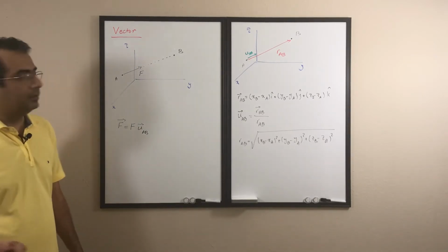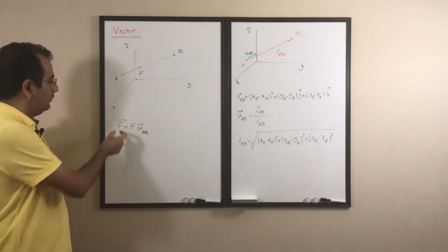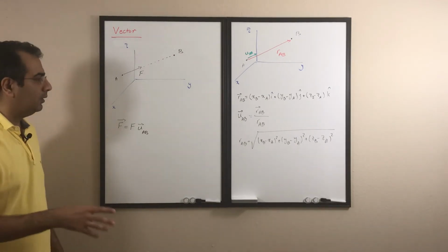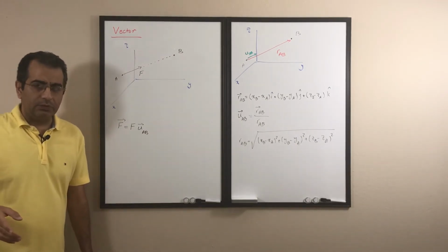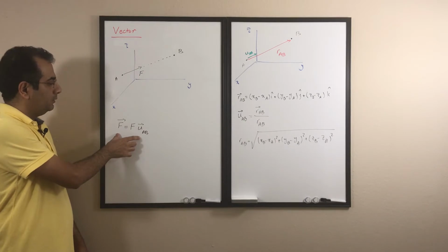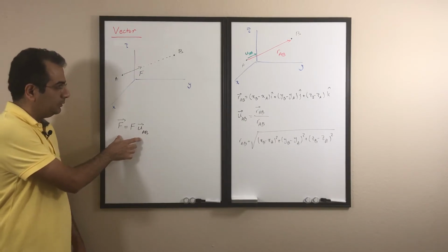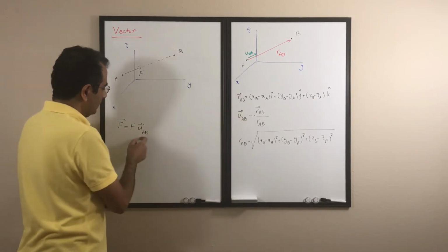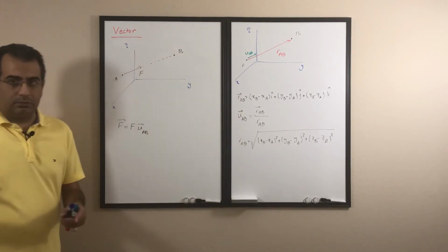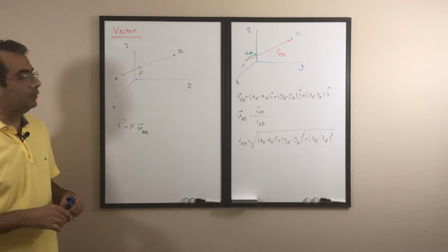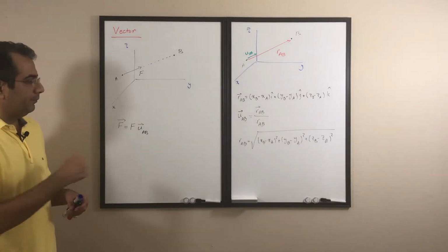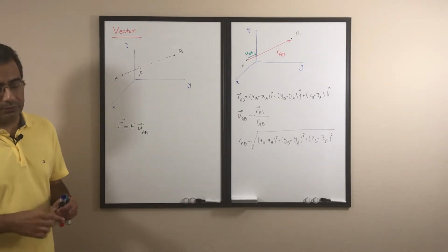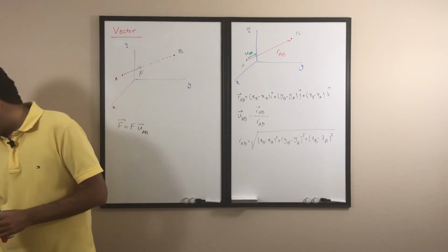That's how we will find the forces in 3D. In almost all the 3D problems we are doing, that is the only equation we need. And these two are the way that we calculate the unit vector. So that's the basics of how we deal with vectors in 3D format, or in the Cartesian method.